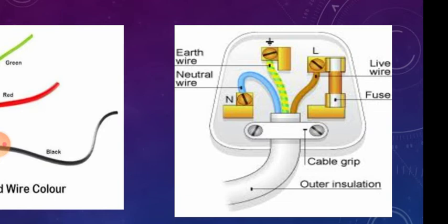So how can this large amount of current be generated? It may be due to a fault in the equipment, or the plastic coating on the live wire and neutral wire going away and they come in contact accidentally. If the neutral wire and live wire come in contact with each other, then a large current will flow in it, producing heat.